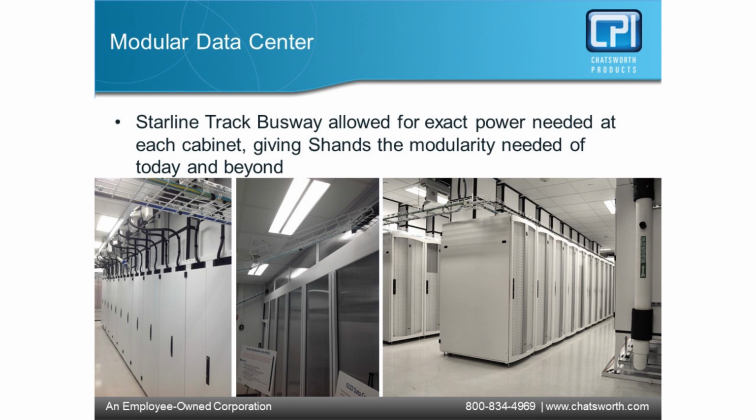Whereas with hot aisle containment, you could provide more than 3 times the amount of air volume in the space to cool devices, so you could ride through some of these hiccups that happen. And this is a regular thing that happens within our data centers. So from my perspective, I'm a hot aisle containment person.